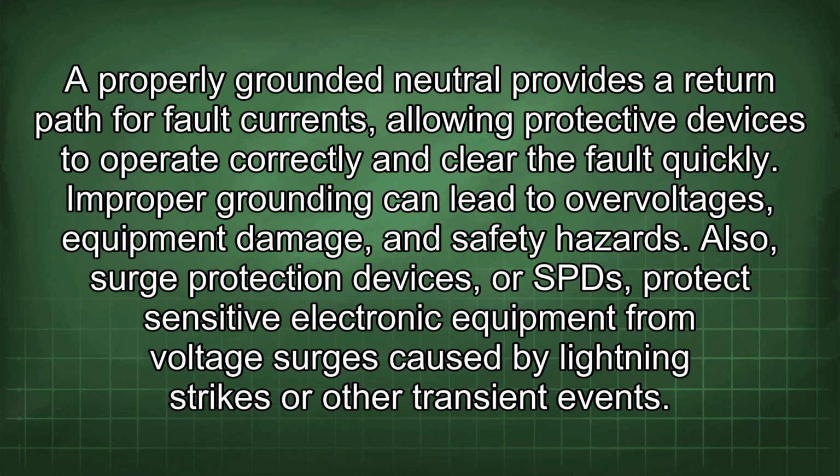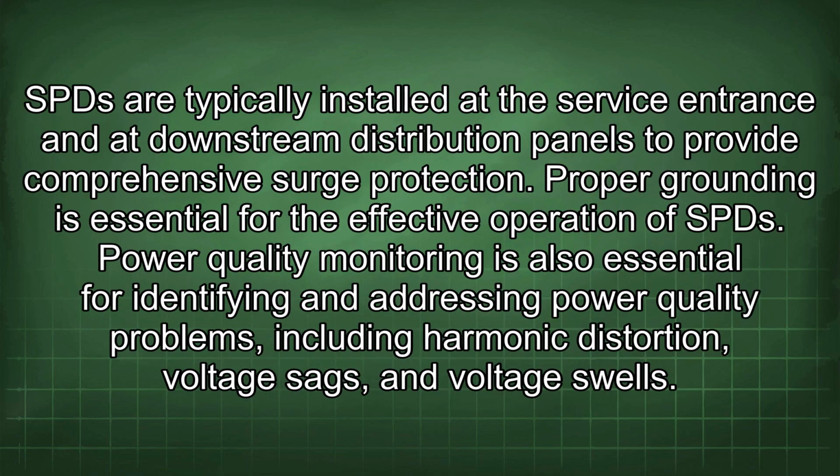Also, surge protection devices, or SPDs, protect sensitive electronic equipment from voltage surges caused by lightning strikes or other transient events. SPDs are typically installed at the service entrance and at downstream distribution panels to provide comprehensive surge protection. Proper grounding is essential for the effective operation of SPDs.